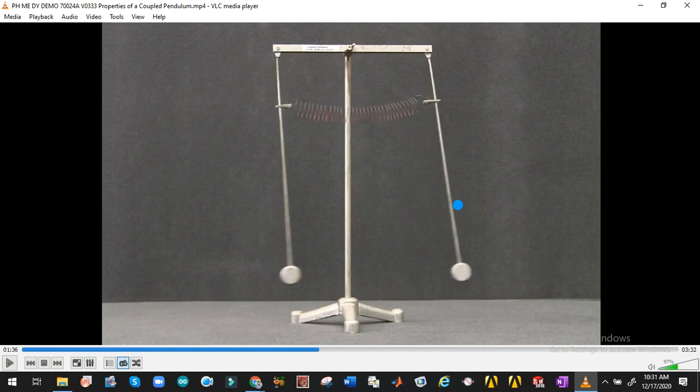It acts like a second mass, and motion transfers from the first mass to the second mass, energy is dissipated by the second mass, and the first body comes to rest. This is how we can control the magnitude of the first mass, because the primary mass is the building, and we do not want our building structure to be excited at a maximum amplitude. So we always want to control its motion amplitude.